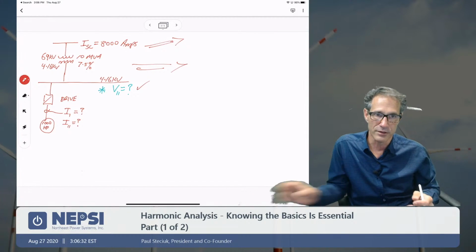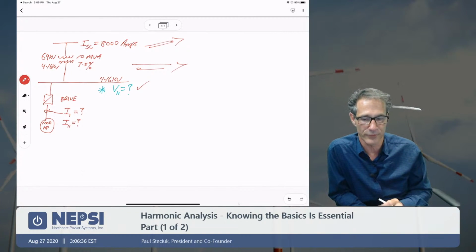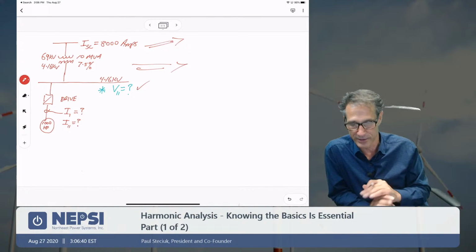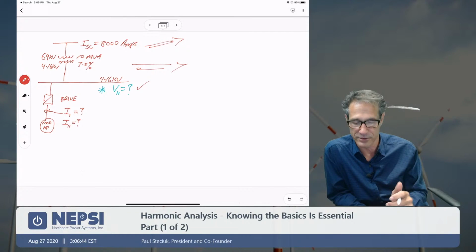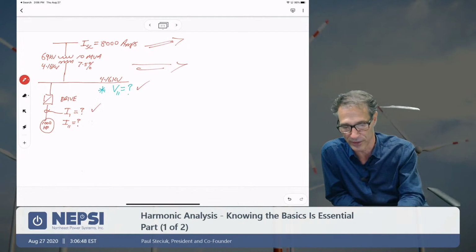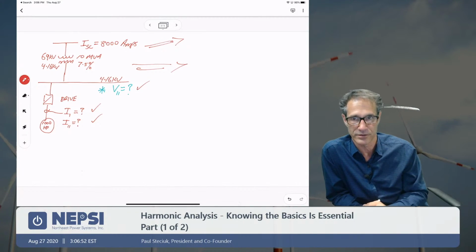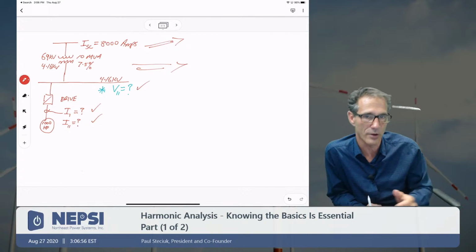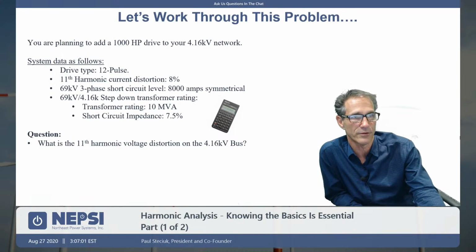A lot of times you see the low voltage capacitor suppliers coming up with rules of thumb, harmonic penetration percentage of secondary load. I say forget all those tables. To some degree they're baseless tables, and actually go back and do the calculation because it's very easy to do. By assuming just this data here, by assuming the impedance data and doing basically Ohm's Law. So we're going to skip that for this week because we don't have time.